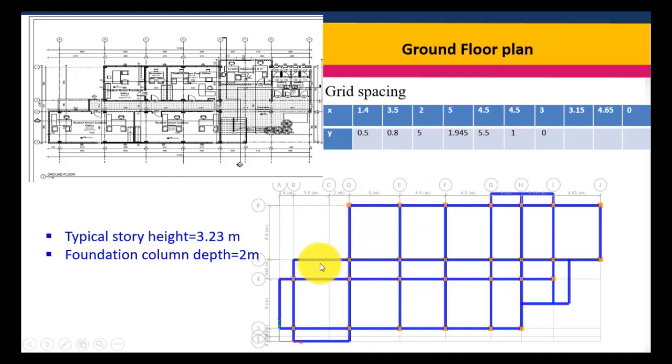Next, here the beam length is extended up to 3.5 meter. Therefore a 3.5 meter by 1.945 grid beam should be drawn here. Another, here we don't have any cantilever beams, and those should be deleted. Another, here we have secondary beams that extend in the 2 directions.